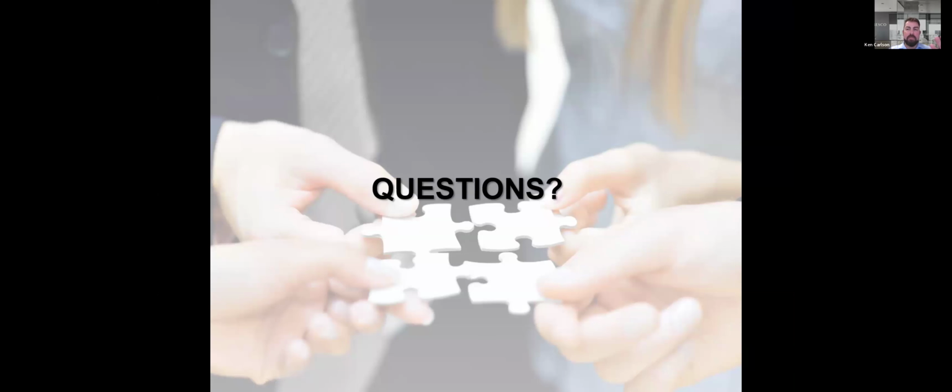If you did do something like a multi-zone split system, just so that everybody's aware, a multi-zone, depending on the size, has multiple ports. A multi-zone at 24,000 BTUs has like 2 or 3 ports. When you get up to like 48,000 BTUs, I think it's got 5 or 6 ports. That basically means 5 or 6 heads that you can attach to that unit, but you don't have to.